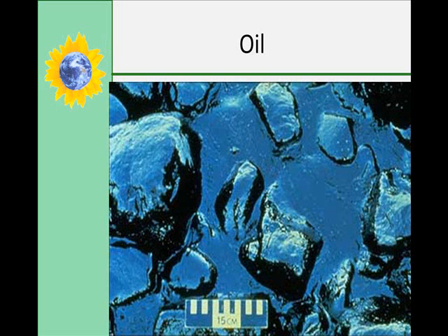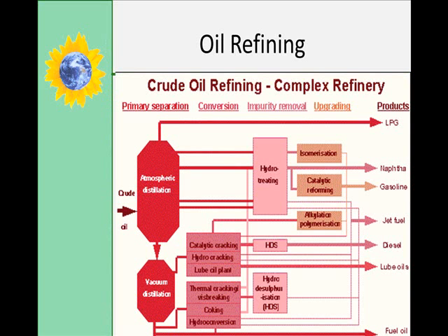The oil refining process separates crude oil into different hydrocarbons and removes impurities such as sulfur, nitrogen, and heavy metals. The first step is fractional distillation, a process that takes advantage of the fact that different hydrocarbons boil at different temperatures. In a tall tower called a fractionating column, crude oil is heated until it boils. Horizontal trays divide the column at intervals. As the oil boils, it vaporizes, and each hydrocarbon rises to a tray at a temperature just below its own boiling point. There it cools and turns back into a liquid.